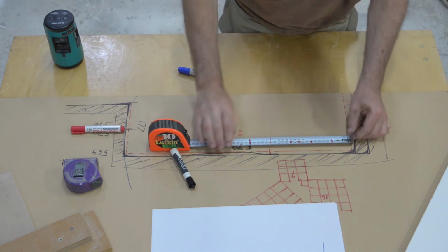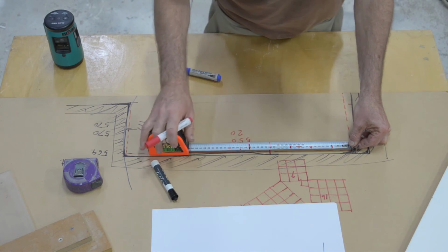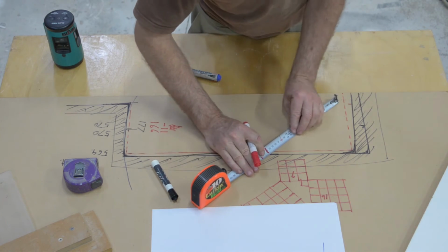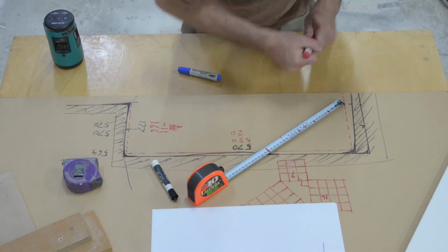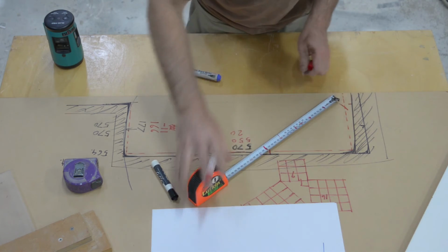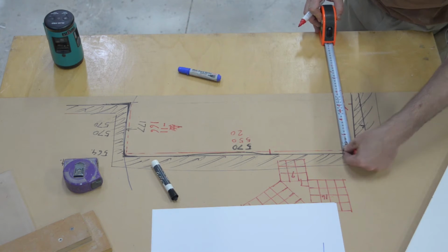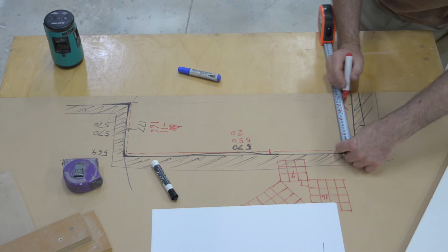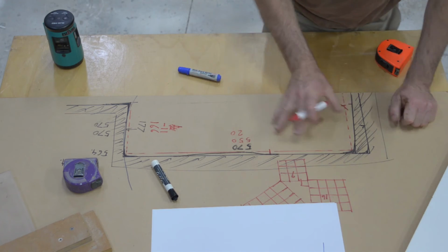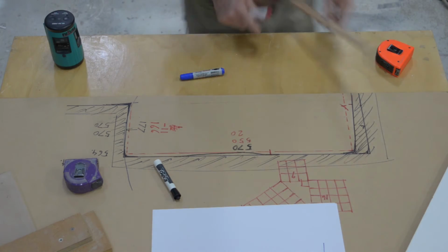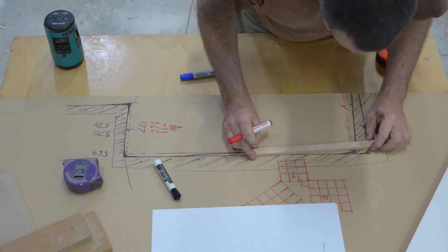trick here. So we're using 50 millimeters as our base unit in this case. So coming out 200 millimeters, going diagonally 250. We could make a mark like that, and then from that point there, we'd mark out 150. Now, here you can see the problem I have. We're actually creating a right angle. Okay, so by doing my little 3, 4, 5 triangle here, I ended up creating a triangle in this location.